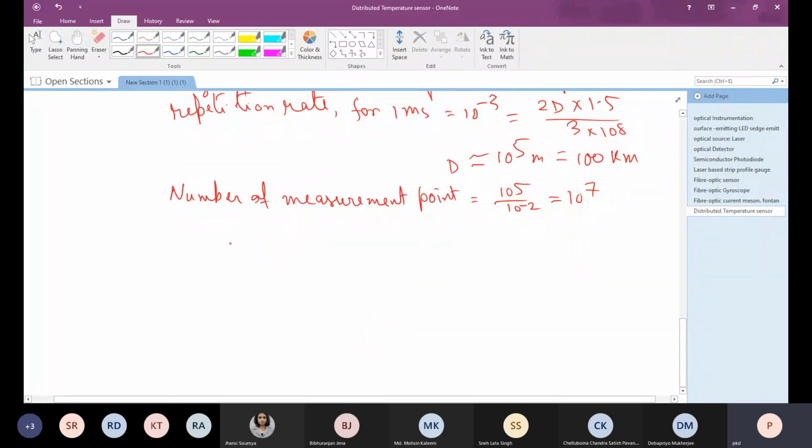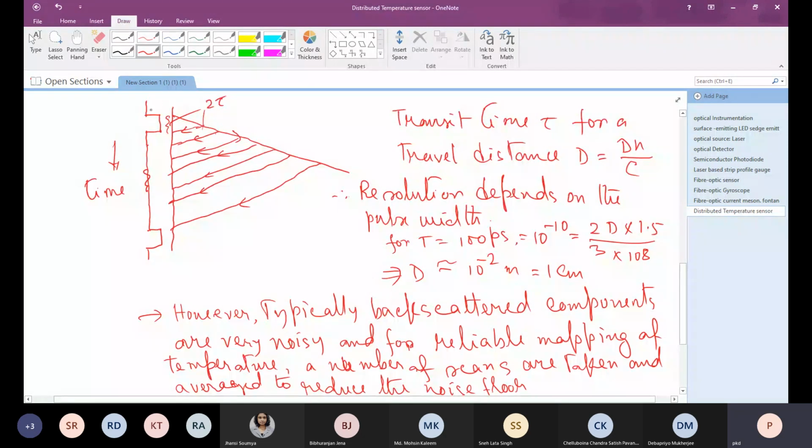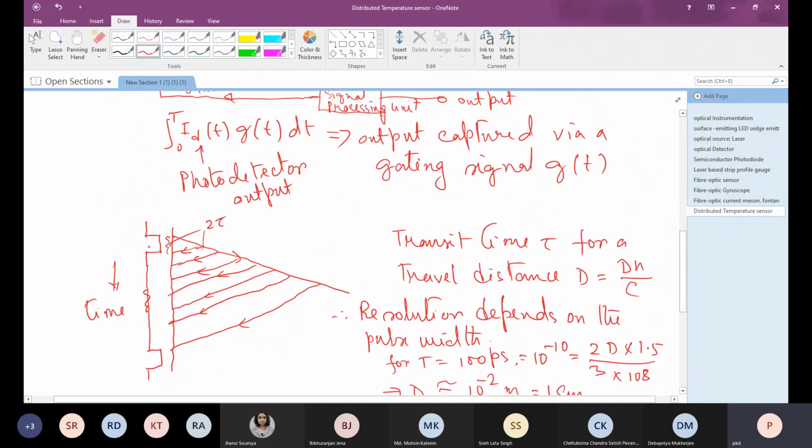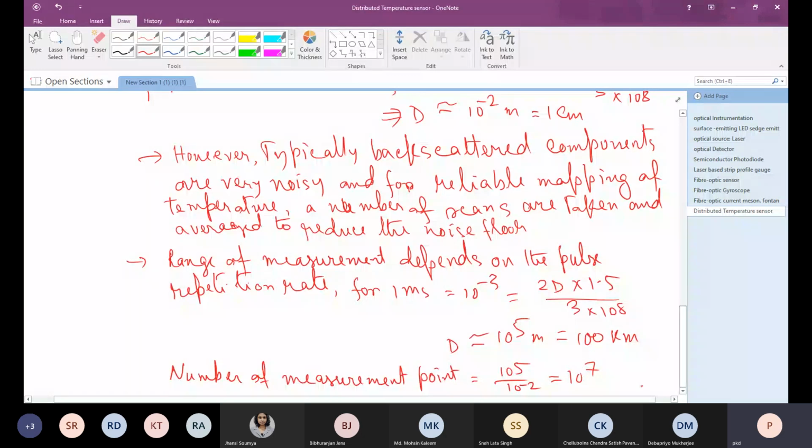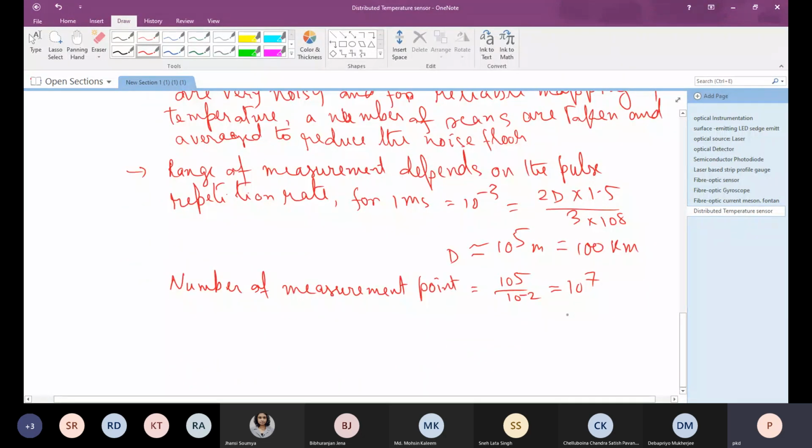So therefore, basically, the counter that is generating the shift, which is shifting this pulse and correspondingly coding it in terms of numbers in time or space, needs to be very high. So typically a 64-bit or 128-bit counter would be required.